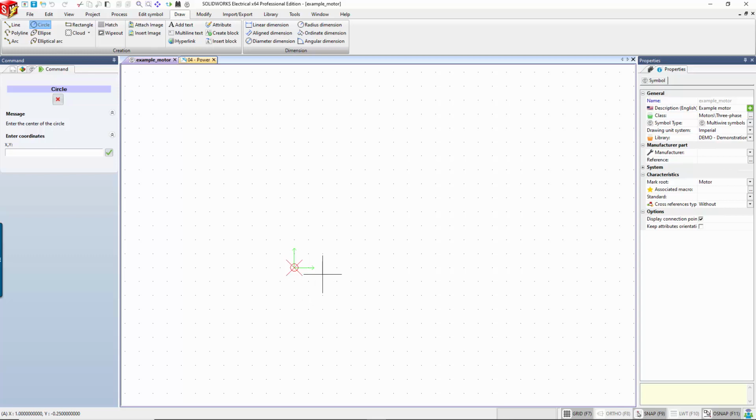and notice my cursor's snapping to specific points on the screen, and that's because I have my snaps on. You can see that it's dark gray and enabled, and that means it's snapping to every 1/4 inch on the page. Having the snaps is important because when you put this symbol on the page, you want it to not look ridiculous with the other symbols that you're using.